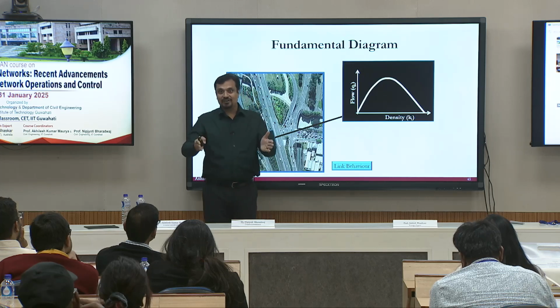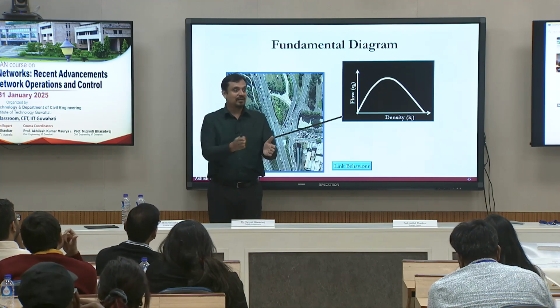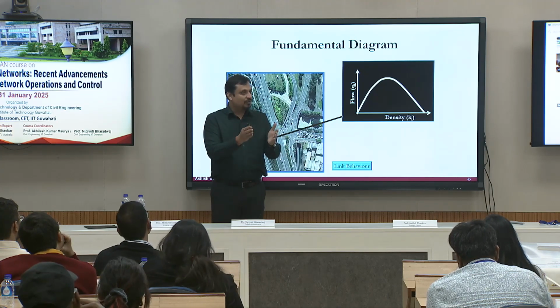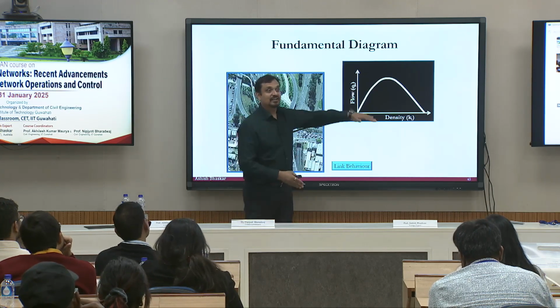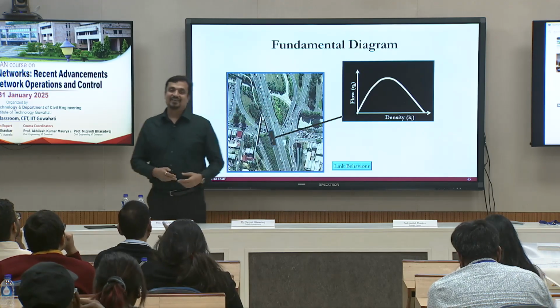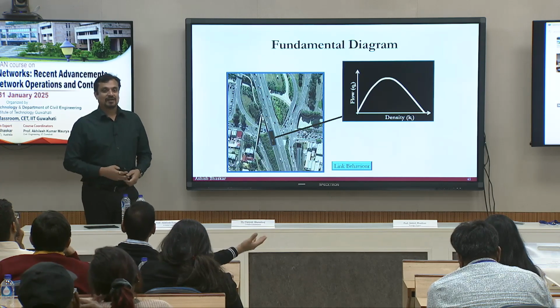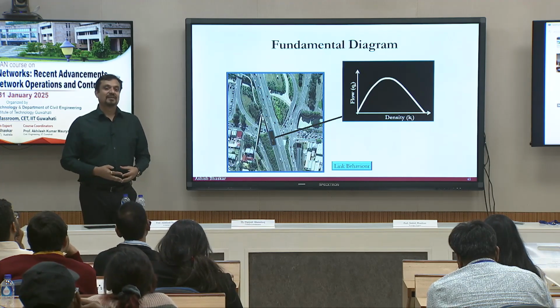But if you do it for the whole 1 minute data point, with average flow and speed, the flow is naturally zero during the red time. So the capacity is lower. Yeah, if we consider the average, then it will come down. During the red signal, all the data will be on the rightmost side. Rightmost side, jam density. Yeah.